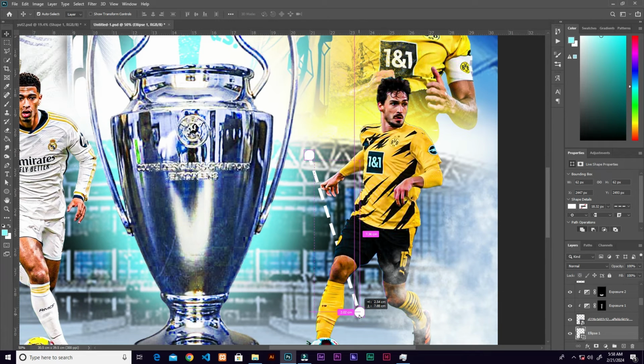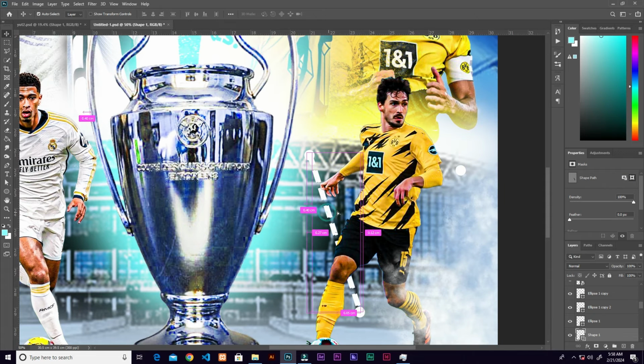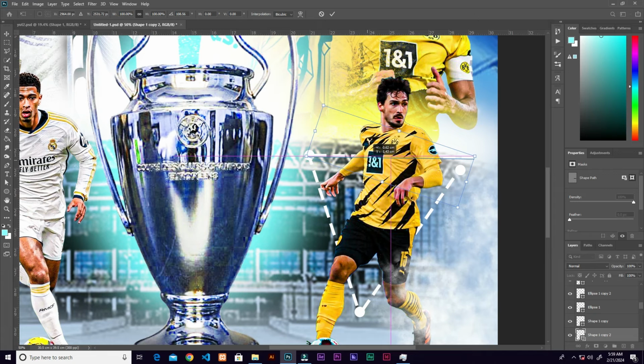Okay, now let's duplicate the last one and then bring it to the top right here. Okay, so it looks like a triangle, so we are going to duplicate the dash line, Alt, click and drag to duplicate. Now let's rotate and try connecting it to the other end. Okay, so we are just creating a triangle out of this, so let's duplicate the last one and then rotate it and connect the top. Okay, so let's go ahead and click OK.